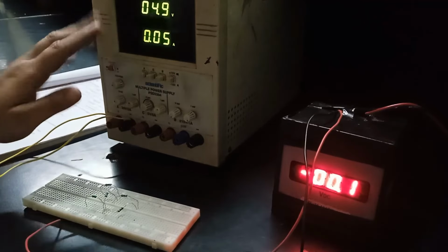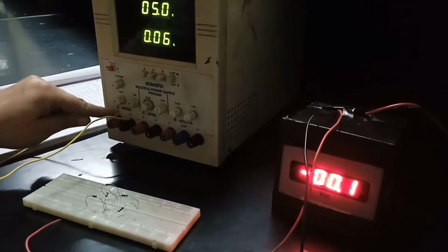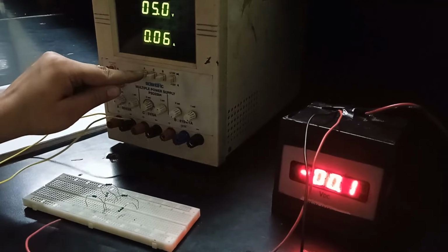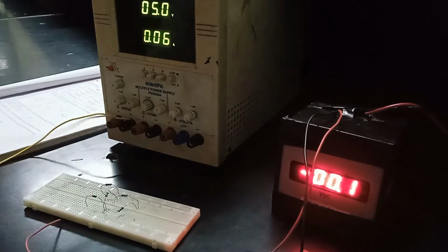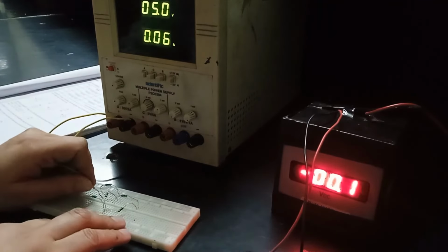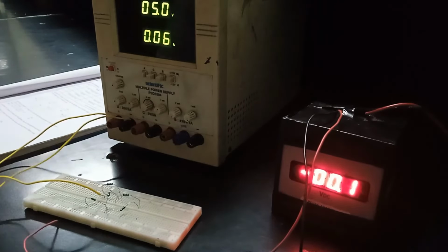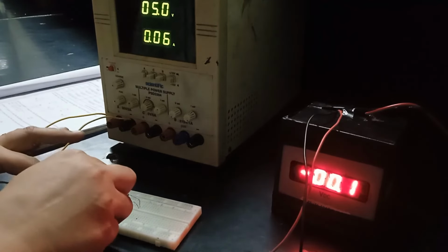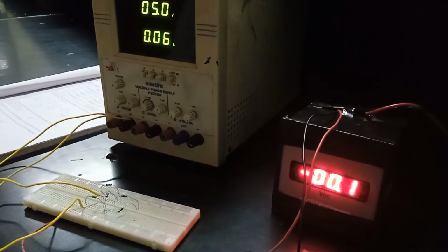So here I have taken power supply, set it to 5 volt first, using channel A, so A must be pressed over here, 5 volt. So initially positive, so positive is connected with the first terminal of R1 and the negative is going to be connected with the other terminal of R5. So these are our connections for KVL, Kirchhoff's voltage law. Now let us start checking the value of our voltages one by one.